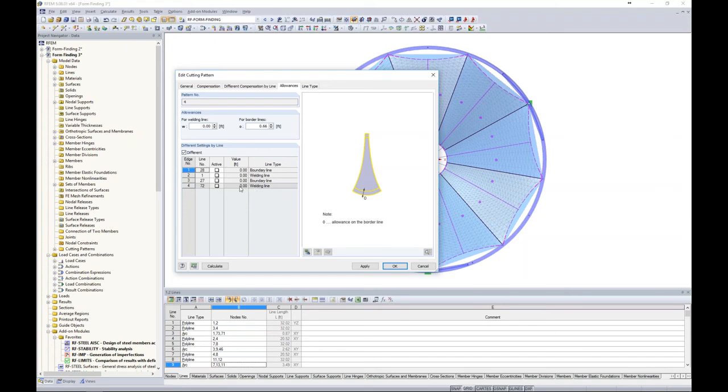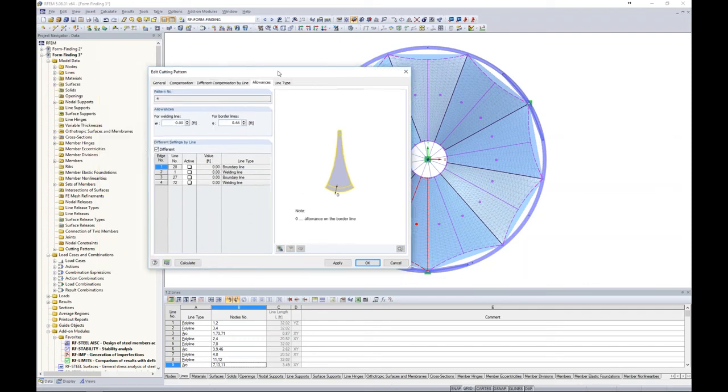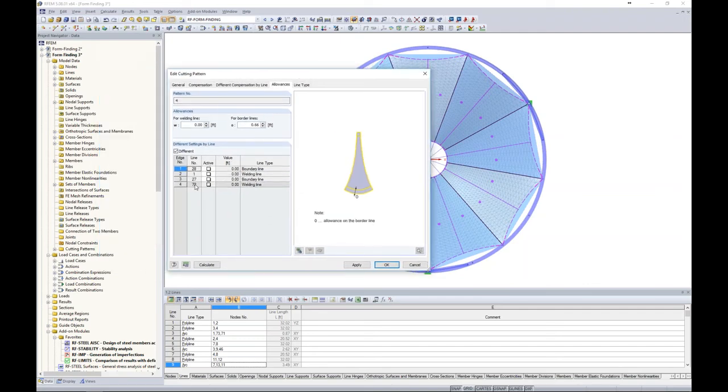For example, taking a look at line number 72, which by the way, we can always activate our numbering for our lines back in RFEM and have those on in the background as we're looking within this dialog box if we don't know which line number 72 is. But I'd like to activate this because my adjacent membrane may be overlapping this a bit.